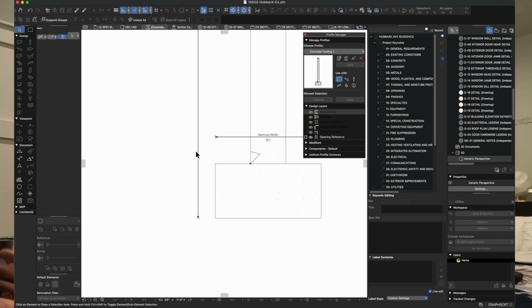Now, surprisingly enough, Salt Lake City, although it's a desert, is in a lake bed. As I mentioned, we have high liquefaction danger in earthquakes. The soils tend to have really high groundwater. In fact, the groundwater is often as high as 3 to 5 feet below the surface. So you'd be surprised at how much water there is in a desert.